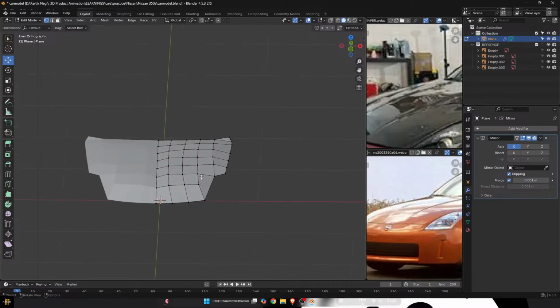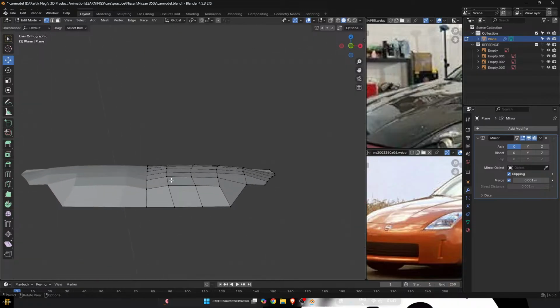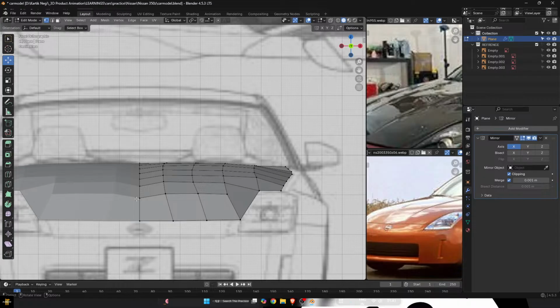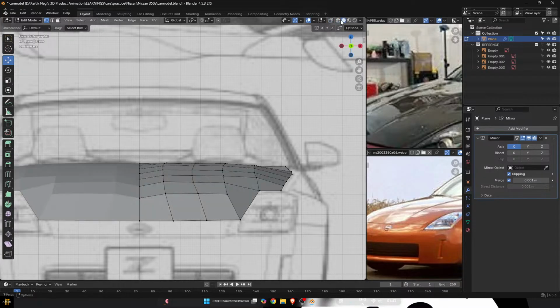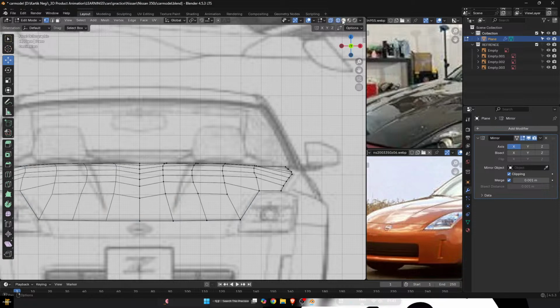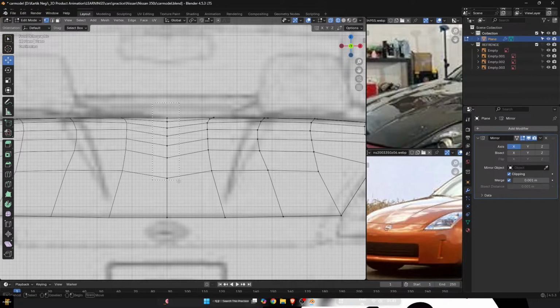Now what we are left with is, just trying to solve this. You can just go into wireframe mode by clicking here, or what you can do is just click on Shift Z. Just take it and move it upward.